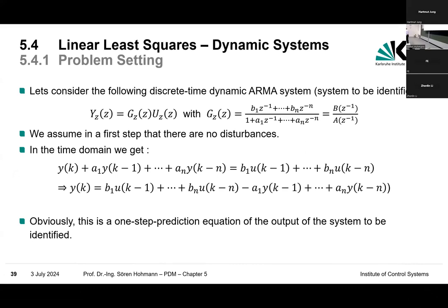You know the past values of Y, you know the past values of U, so you can predict exactly the actual step. YK always indicates the time, if you like. Of course, this is a sampled data system, meaning you have sampling instances. Okay, so a prediction is possible. Well, it seems reasonable, isn't it?